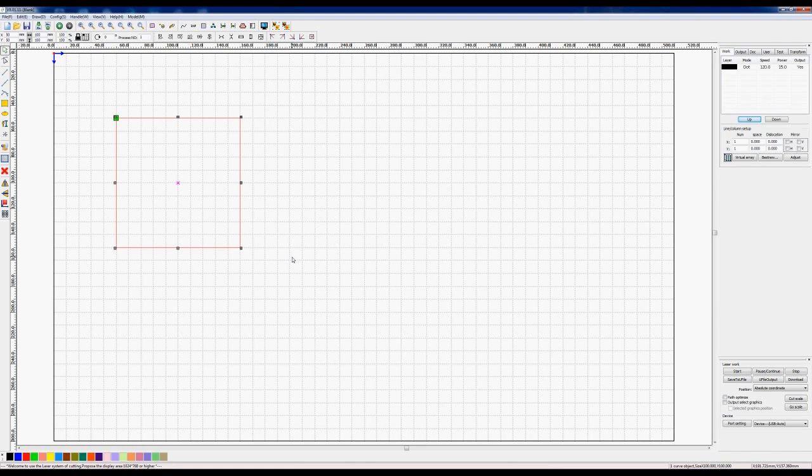That's because nothing has changed on the drawing except the position of the location handle itself, the reference object handle. And it's now moved to this corner here, which is no longer 100, but it's at 50-50. So my object is now moved around by its corner point, not by its center point. That is an important thing that you should remember.